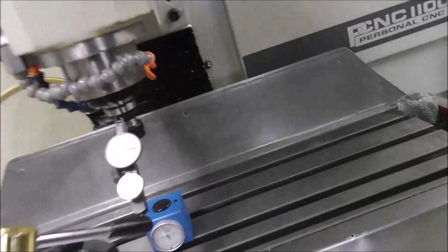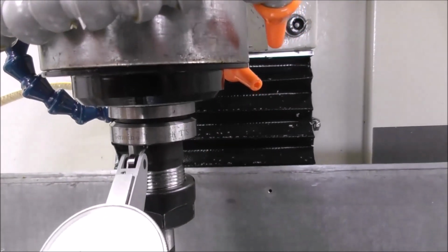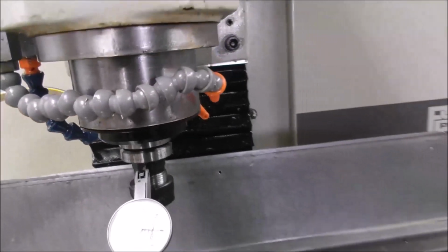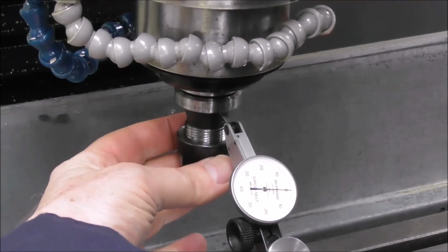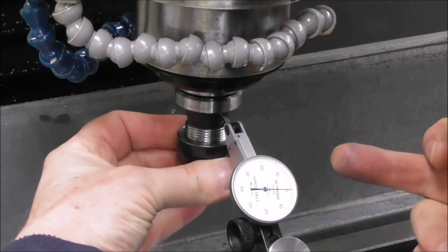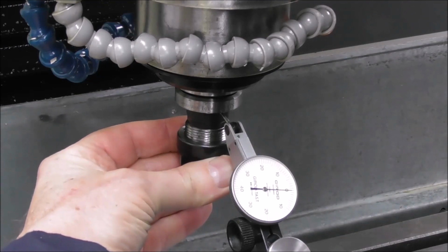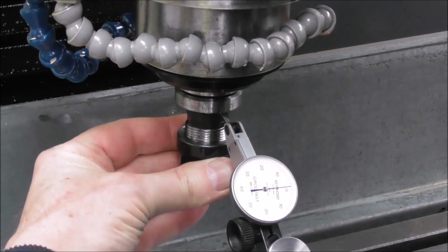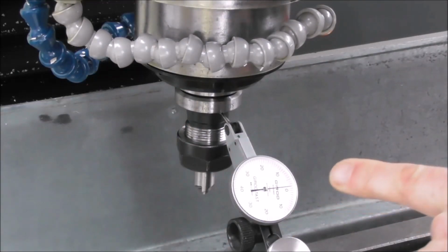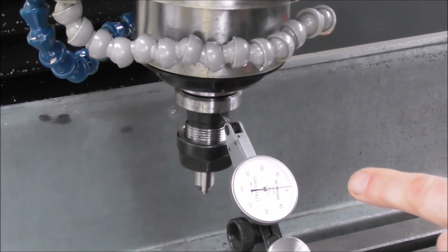I don't know whether any of you have taken the time to measure it, but you get errors there. I'll just set the camera up on a tripod and show you what I mean. Okay, so we've got a 1/100th of a millimeter dial indicator under the flange there, set on 0. You can see it's in contact there, I think. Now if we put the normal tension of the drawbar on there, have a look at the needle. It's moving up over 2/100ths of a millimeter under normal drawbar tension, and that would be the same with a power drawbar, perhaps even more.